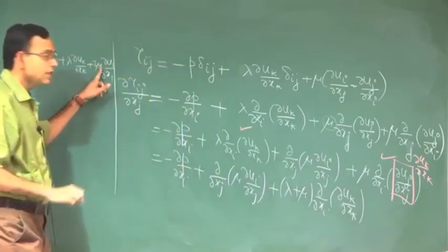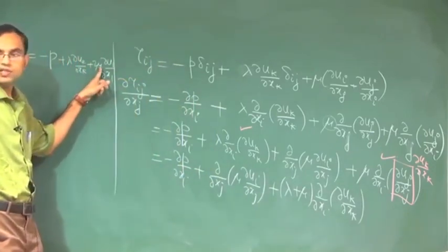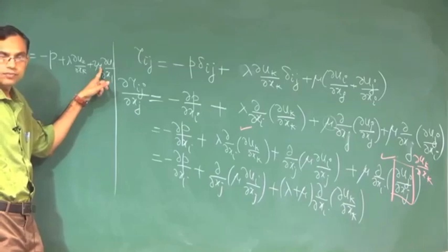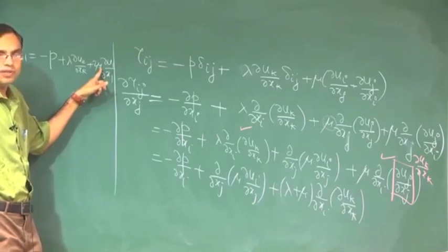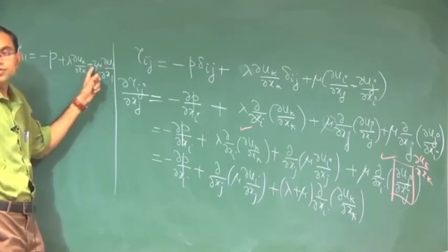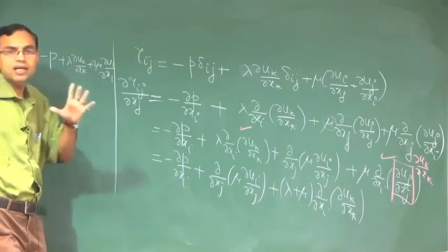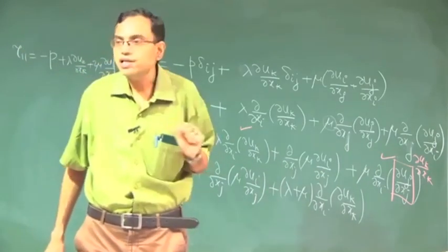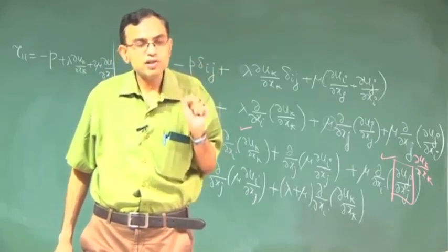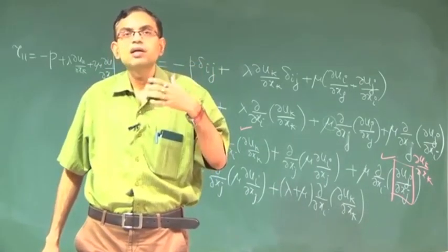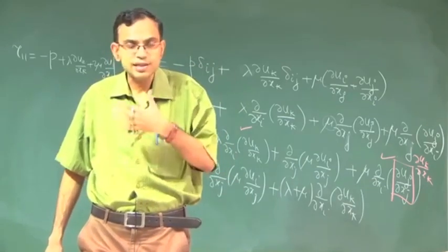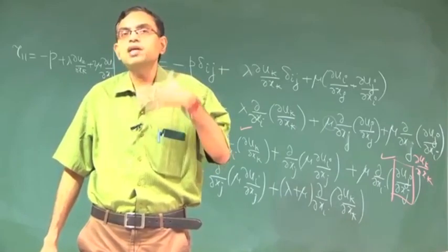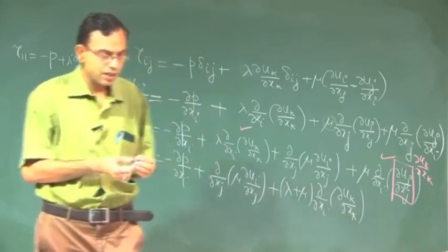See this term, this is called the viscous normal stress. This term is there because of the linear deformation coupled with viscosity that is giving rise to a normal stress. So, viscosity does not just give rise to shear stress, it can also give rise to normal stress. This is something which is not explicitly taught to students, but I think this must be explicitly told.